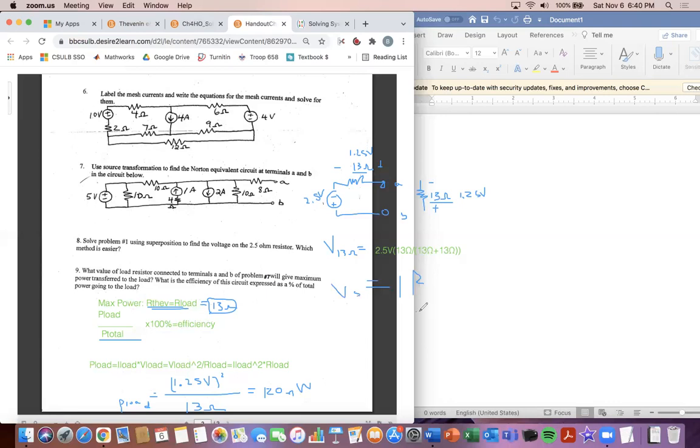And so we're going to have 26 ohms because it's going to be the R load plus the R thev in this completed circuit. The current we don't know, but the voltage from the source we know is 2.5 volts. And so if we solve for I, the current going through the circuit would be 2.5 divided by 26 ohms. For our specific current, let me write it down here. I is equal to 96.15, and that'd be milliamps.